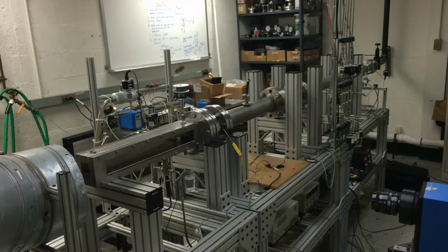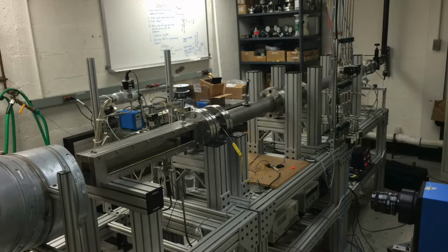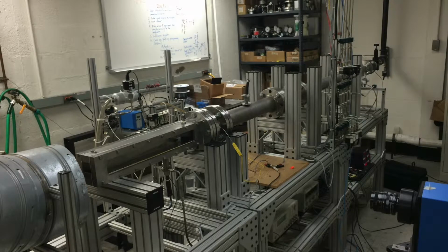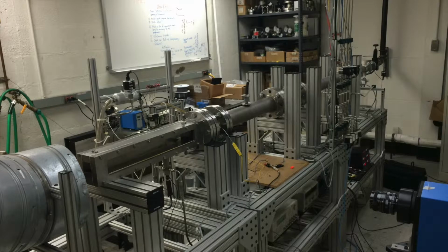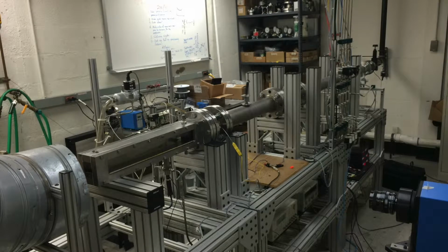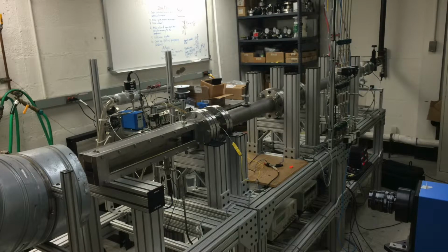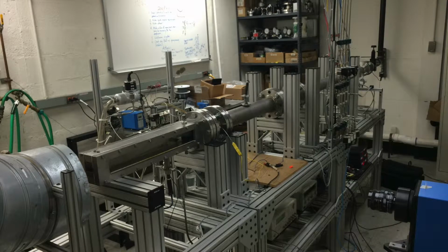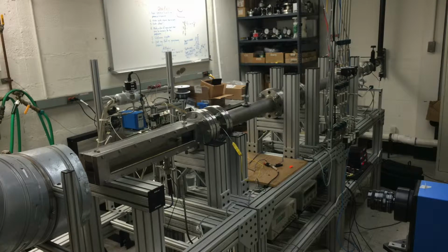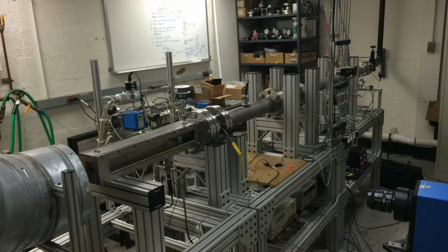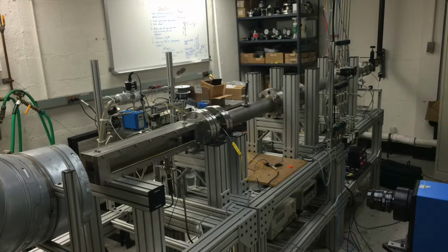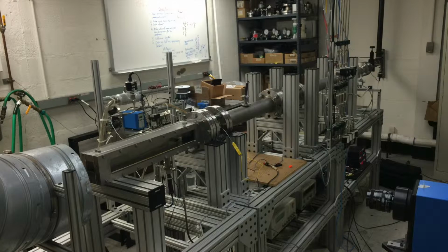Group 1 will characterize the afterburner for a flow speed of 30 meters per second, which is us, and we won't worry about Group 2. Each group will vary the afterburner/augmenter equivalence ratio and measure dynamic pressure inside the augmenter for each case. Once the range of the augmenter equivalence ratios is covered, each group will note down the observed flammability limit and blow-off limit. FFT and spectrograms showing how frequencies change from run to run will also be reported.